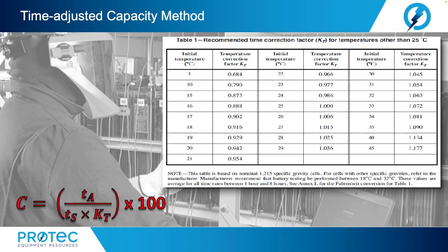In the current version of the IEEE 450, the temperature compensation method is revised to apply the temperature correction to the capacity calculation after completion of the test.